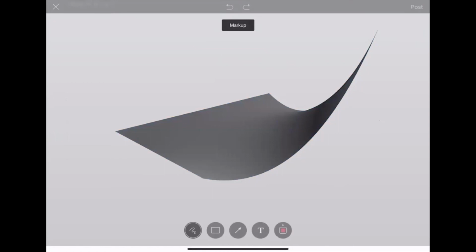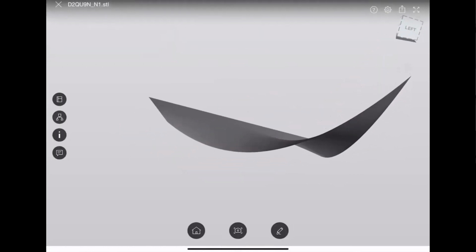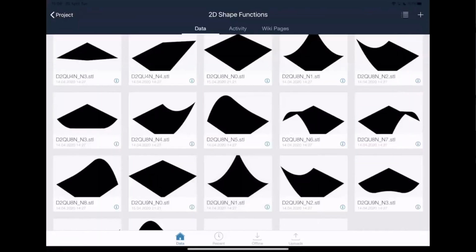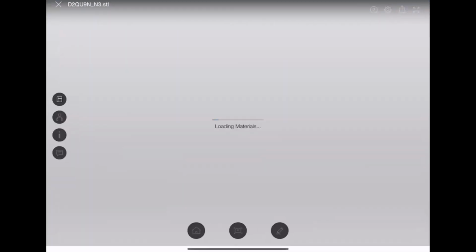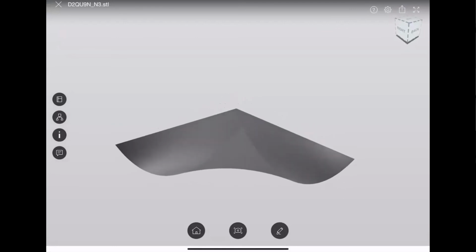Let's see. So the points are, let's say here, or the nodes, they are these points, and they are all 0, okay, the way they are. But then it's exactly 1 at that corner node. So this was N1, and you can imagine N2, N3, N4 for a 9-noded element. They all look similar to this. It's just a different edge is coming up. Okay.